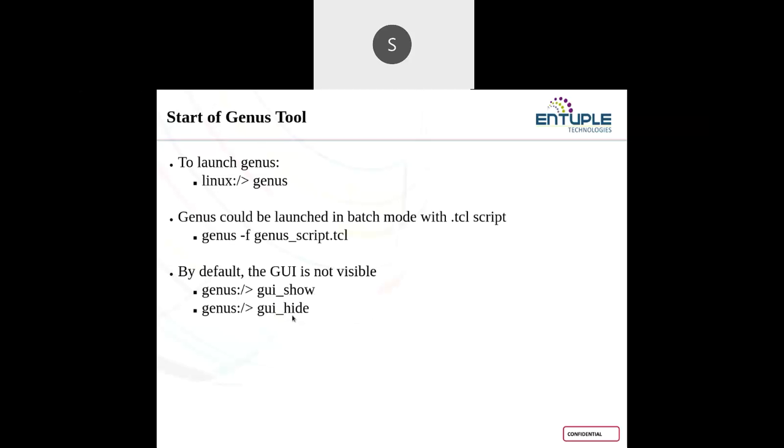These are the additional commands I use in the synthesis tool for seeing the schematic, the schematic view of the gate level netlist I have generated. At that time you can just enable the GUI mode and see it from the GUI mode. Or even the backend files will be generated, and you can go through the backend files also.